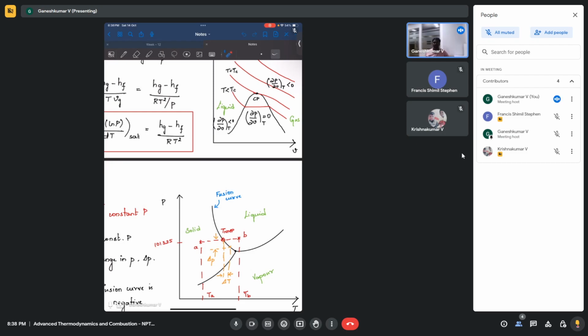So in ANSYS also they will give saturation models, and whoever uses it should know that they need a saturation model and should give it properly to ANSYS. There should be some way in ANSYS, though I'm not really sure about ANSYS. But by default, ANSYS will select some model. It might even select that saturation temperature is the same, HFG is the same, constant saturation models, all those things, and it might do something with that.